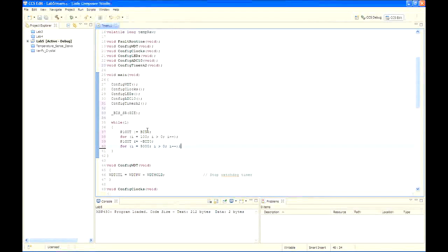This routine doesn't use any intrinsics, so when we're debugging the interrupts, they'll look good in C rather than dropping you back and forth between assembly. Oh, and don't forget to declare i at the top of main.c: volatile unsigned int i.